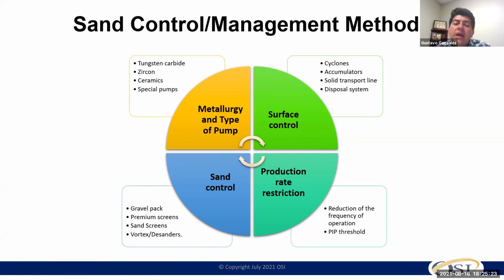But on the other hand, we may go with an initial big pump, and in less than a year that pump is oversized and starts failing due to overheat, because now it's gas locking and my well is down every 20 minutes or every hour. That's the balance that we as production engineers have to go back and design, to be able to take a better approach.